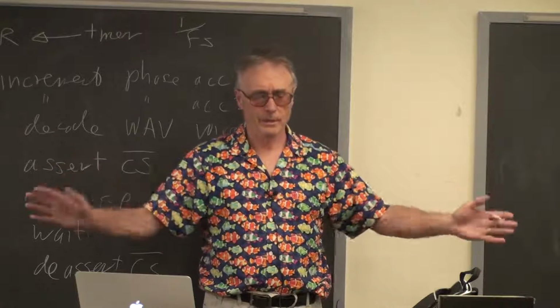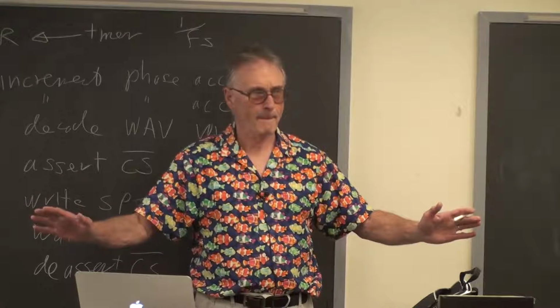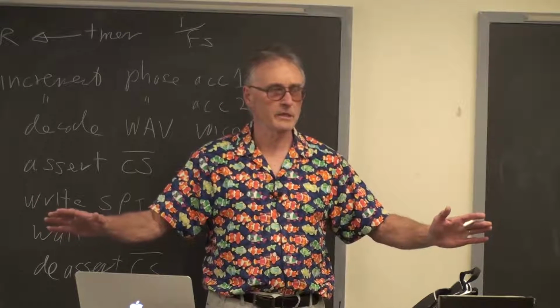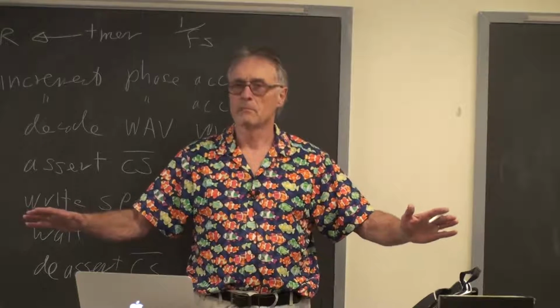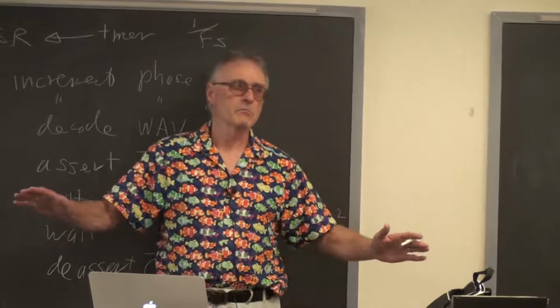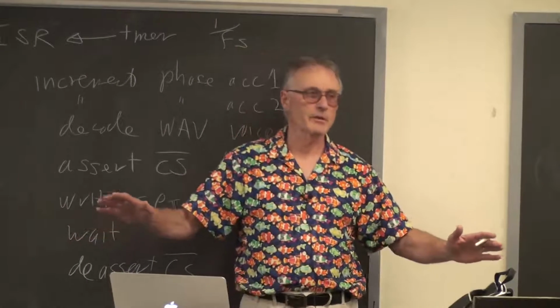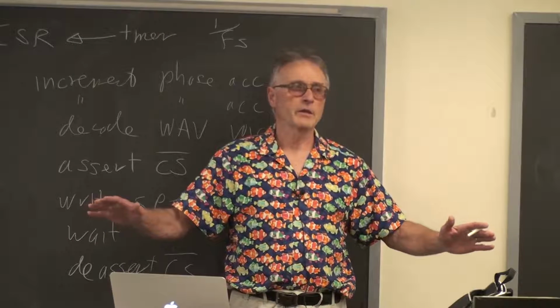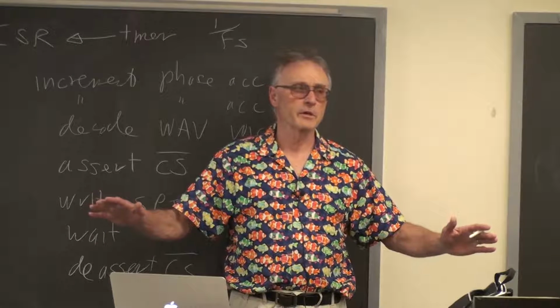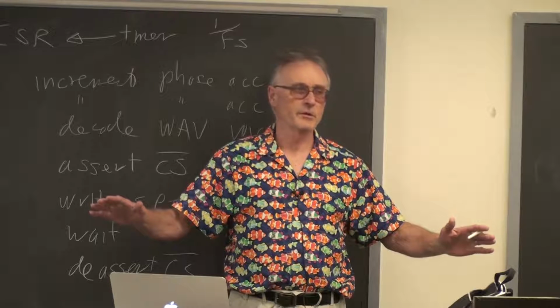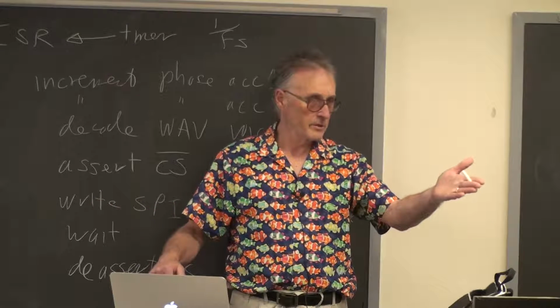We'll talk about DMA later. That's just a quick introduction. It is another bus master. It has very limited arithmetic capability. It can calculate a cyclic redundancy code, and it can move data from memory to memory, and that's about it. Do you have a question?